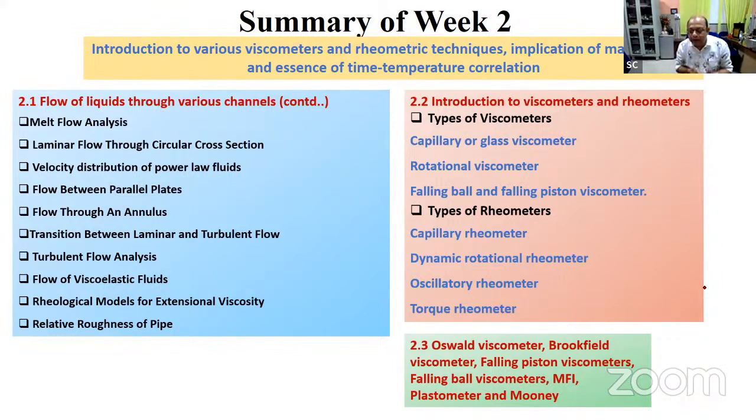Okay. Then I talked about Mooney viscosity, which is again more like a torque rheometer. It gives you a measurement of the torque required to rotate a rotor, which is embedded into the material, and you measure basically the resistance, which ultimately culminates in a measurement of the molecular weight of the material. Okay. So that's what we do for routine analysis, particularly in our industries.